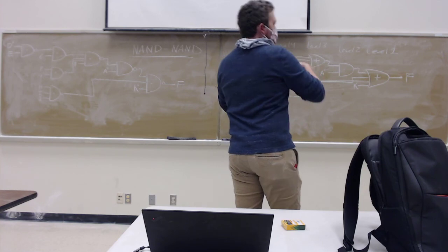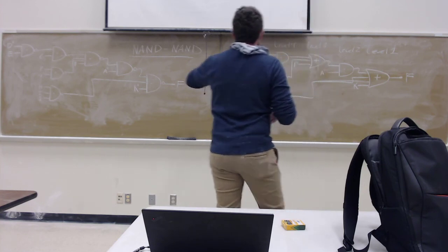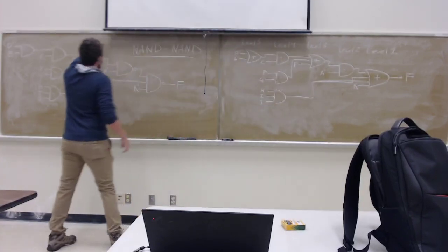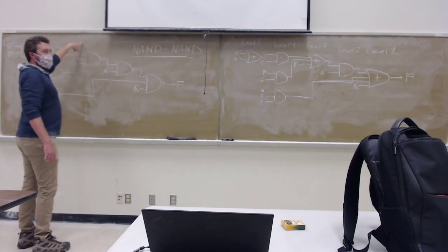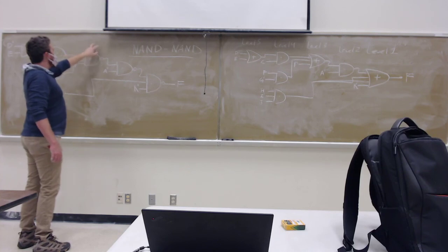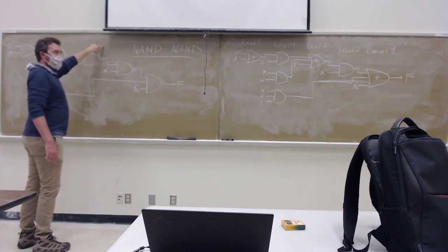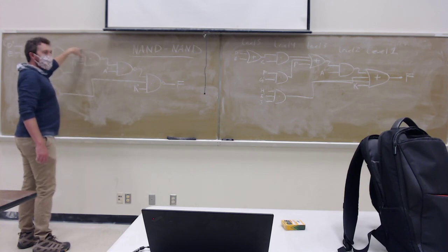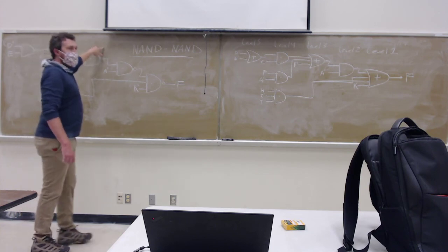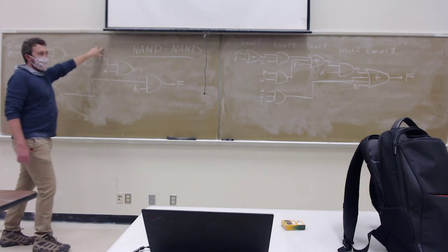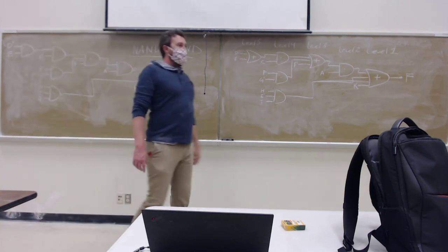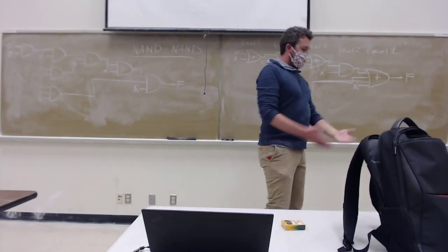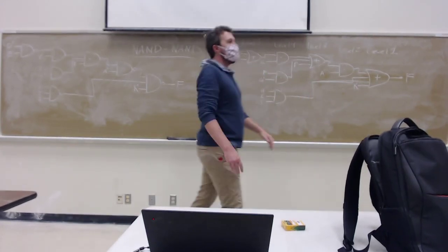you have to start with things that don't depend on other things, right? For example, there was D or E prime, and now it's ANDed with C, right? Which means that the output of D or E prime was going to be the input to that AND gate with C. Which means that you had to do that OR operation first. Does that make sense? Yeah. So you have an OR gate, that's how you do the D and E. Yeah. And then that gets handed to a gate with C.